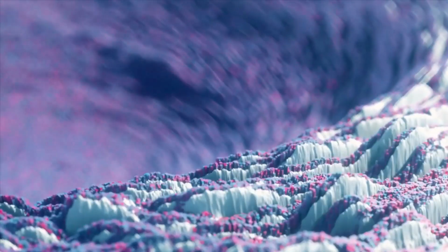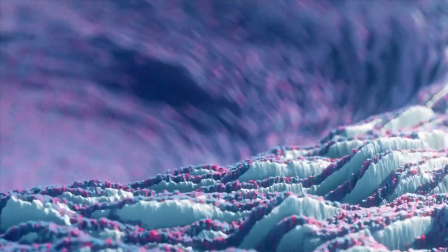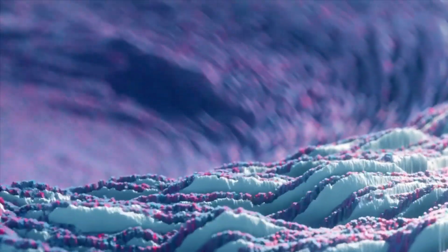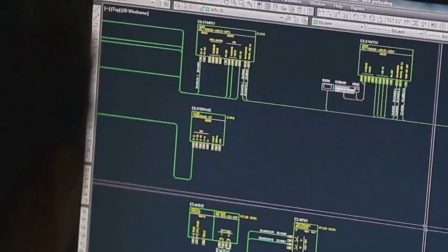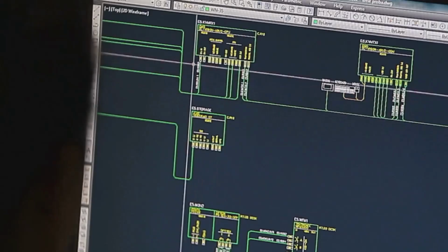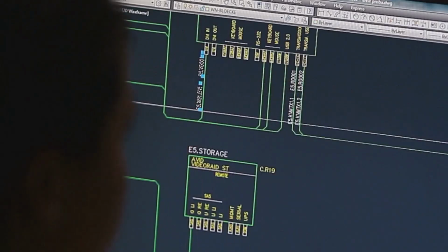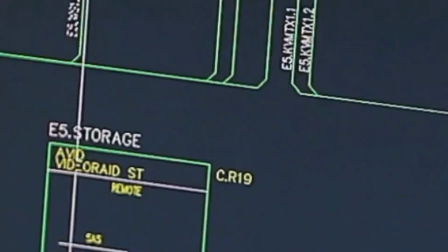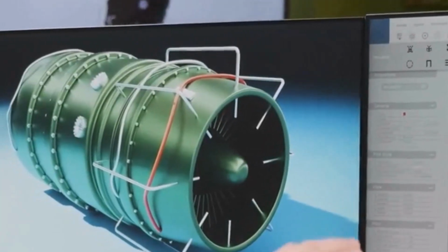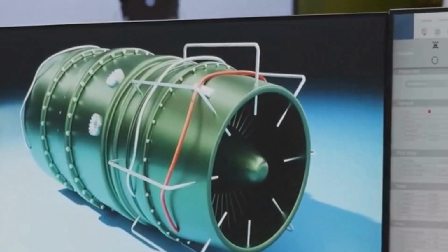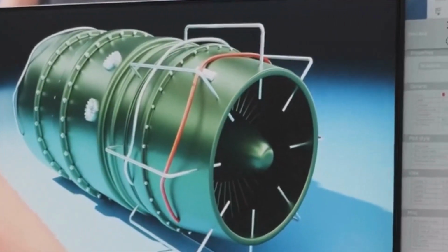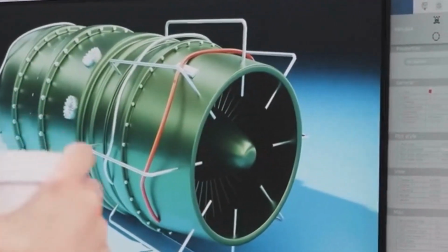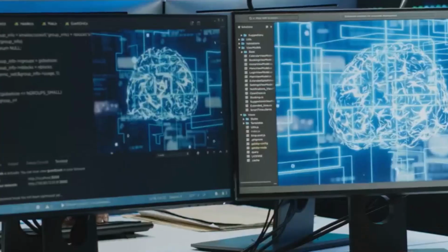It allows the simulation to capture the steep gradients in velocity and temperature that occur only within this tiny sublayer. These gradients are the direct cause of wall shear stress, which creates drag and heat transfer. Without placing mesh cells in this region, the simulation is effectively blind to these critical phenomena, leading to potentially significant errors in the final results and making our engineering predictions less reliable.